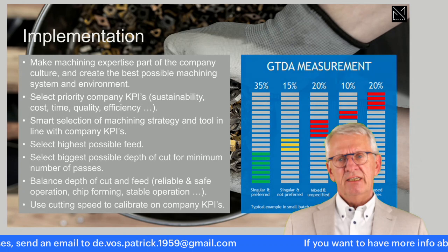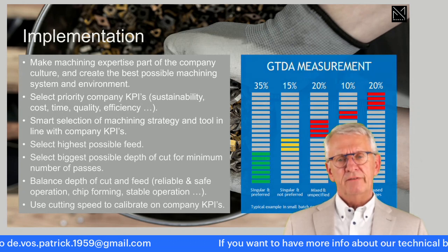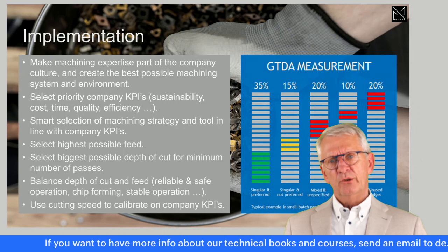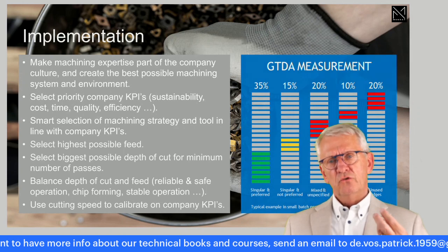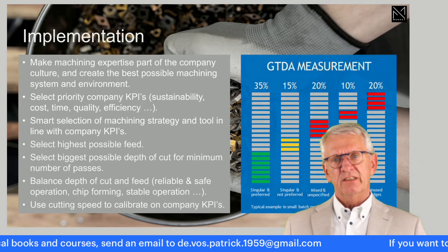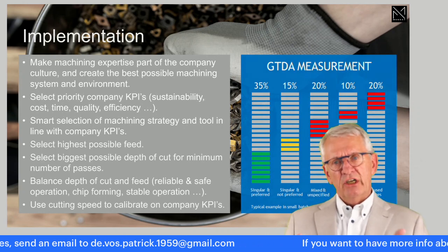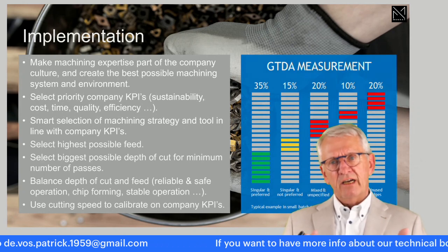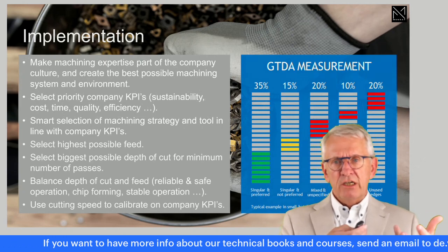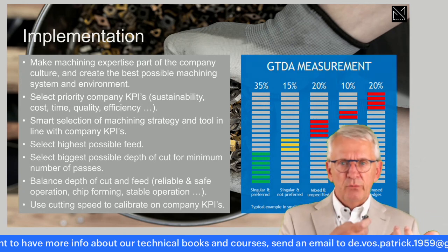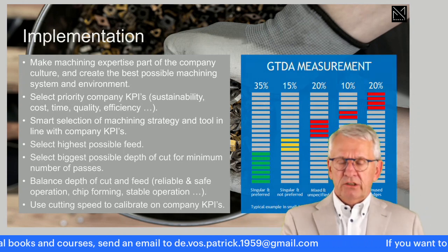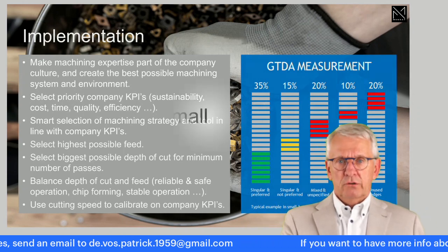Key in this is how do tools behave. And as I said, in small batch production, you don't always have the opportunity to do the traditional tool life stuff and so on. You will have to do a more statistical approach. Look in general, look how tools wear out and depending on in which situation they were used and if what you see is acceptable, non-acceptable, and based on what you observe, correct for the future.